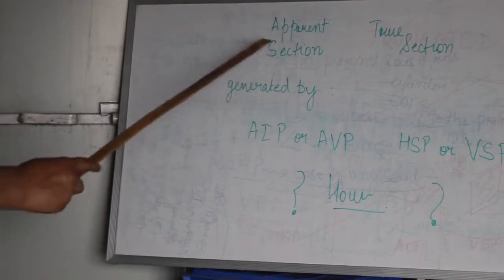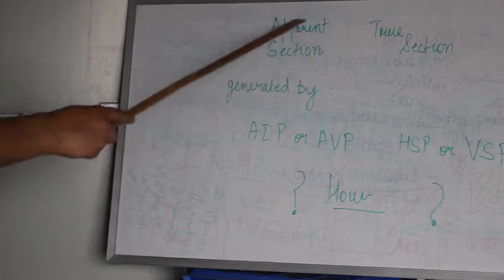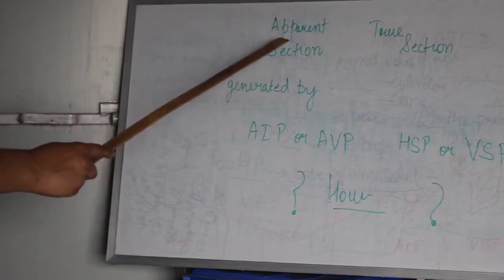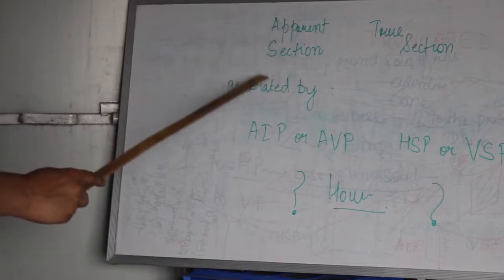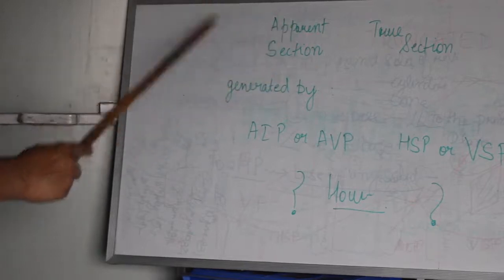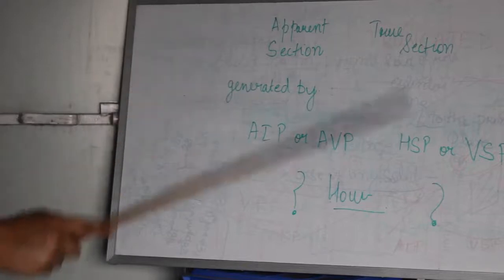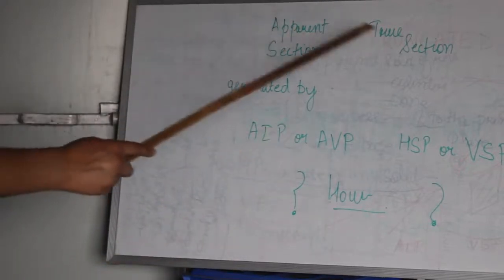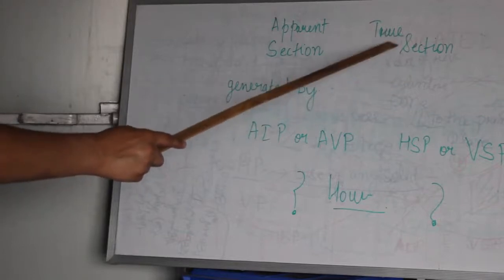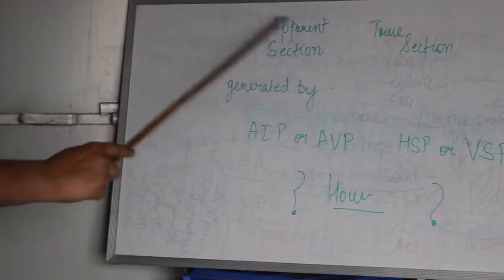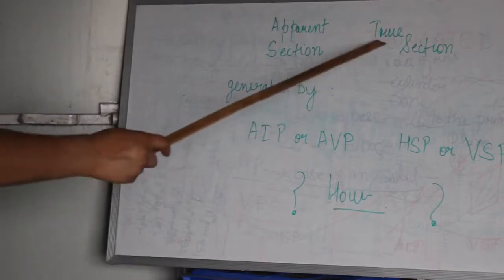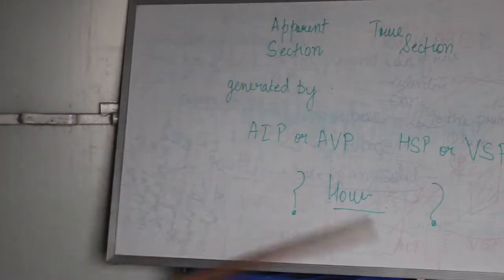Just because if any of the views is an apparent section, whether it is a front view or a top view, then an extra projection is to be drawn in this case, which will show the true shape of the sectioned part, true shape of the sectioned part.